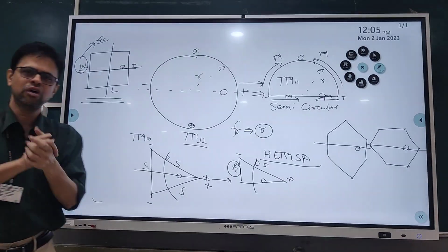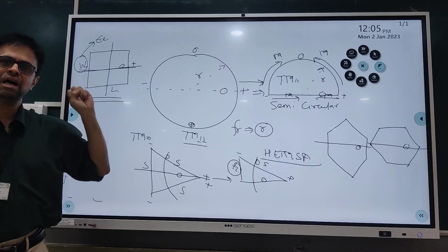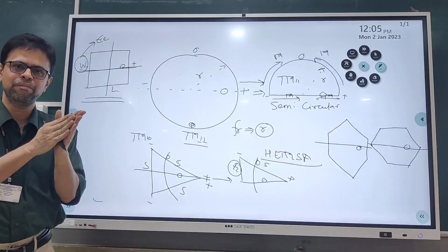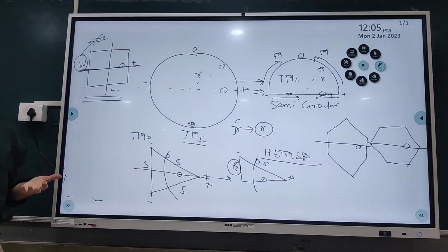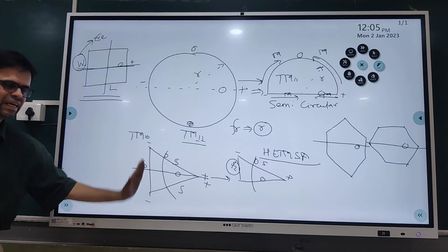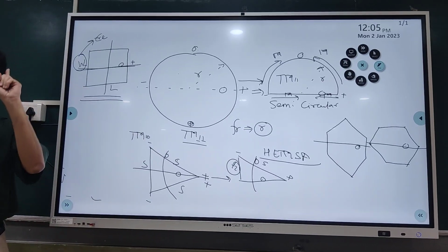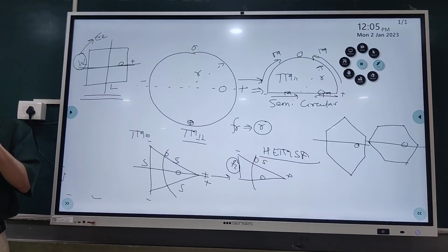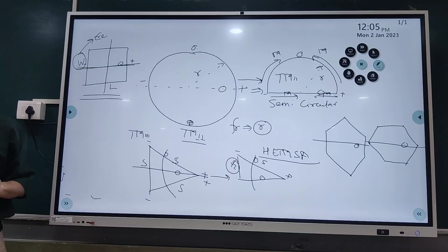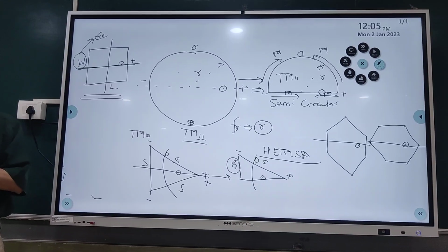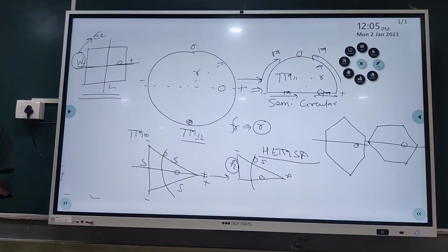Just to put on record, we discussed then that RMSA offers better performance in terms of cross polar level, whereas the ETMSA has a higher cross polar. The same explanation can be seen by considering the magnetic dipole model and the fringing field distribution. So that we have covered earlier.